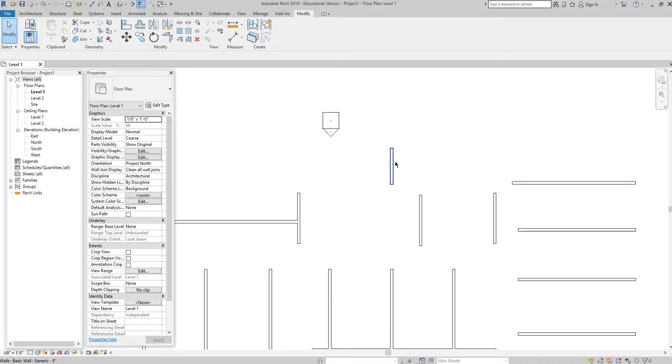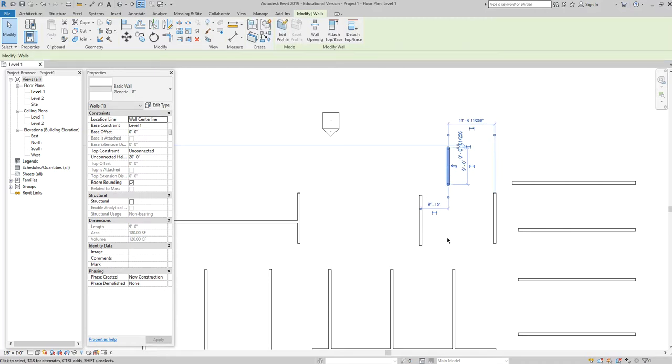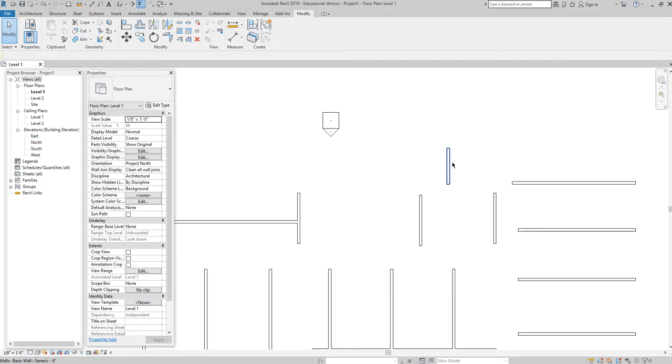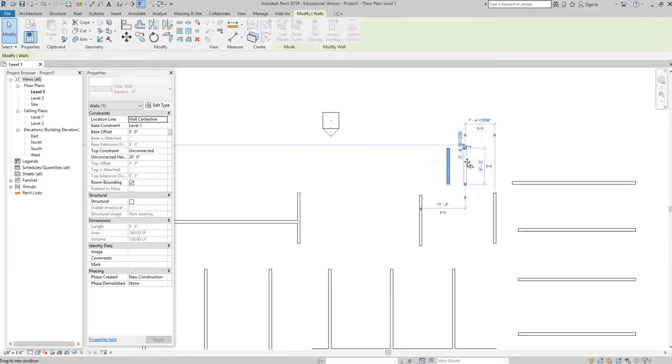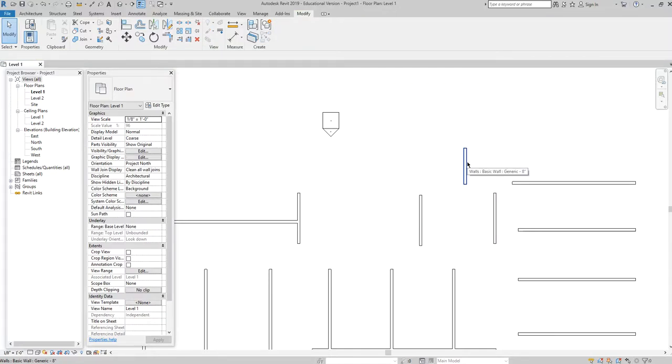And what that means is if I'm in a floor plan view like this, I may see the walls being selected as I drag them across the drawing space here, but maybe I don't see I accidentally picked the floor, right? Or the subfloor or the structural floor below it, or a wall on the level below it, or the whole entire linked model that everybody's working on, right? That you have 80 people working in or whatever. So the drag command, while it's easy and I don't have to type anything and I can just click and drag things, it very easily selects other things and can